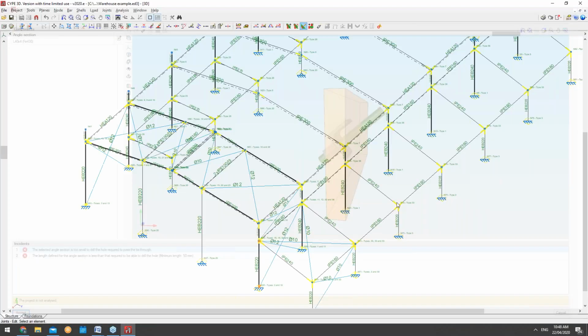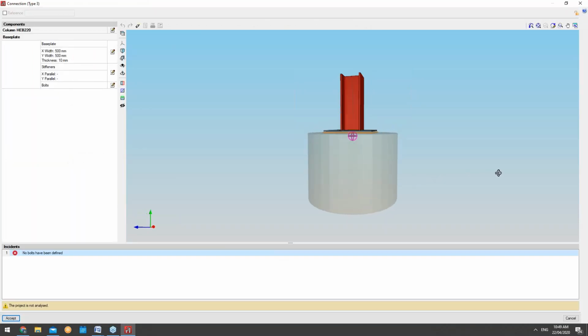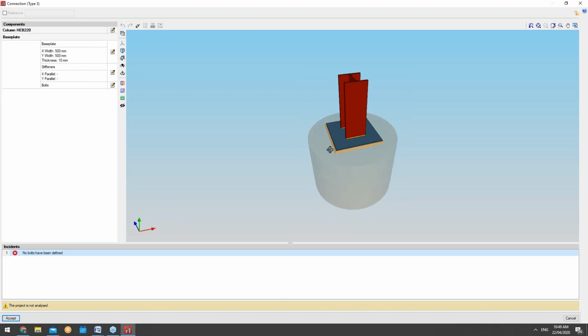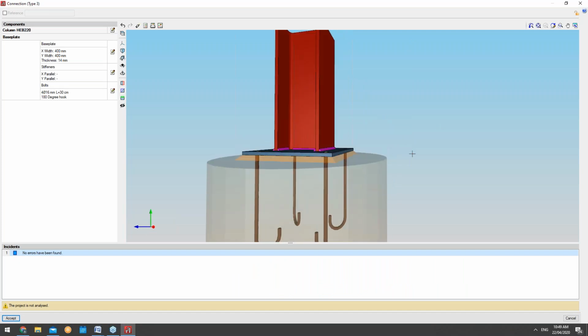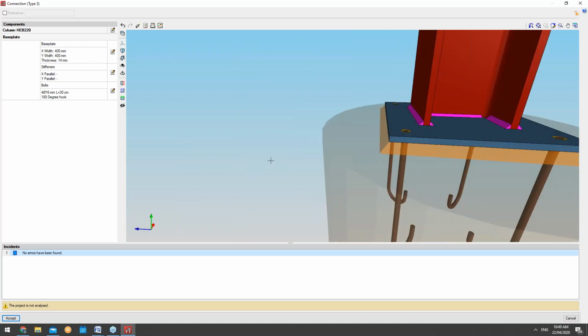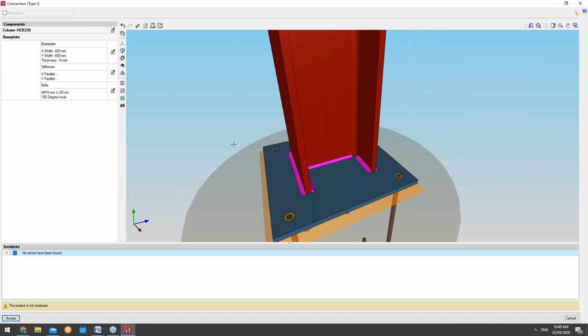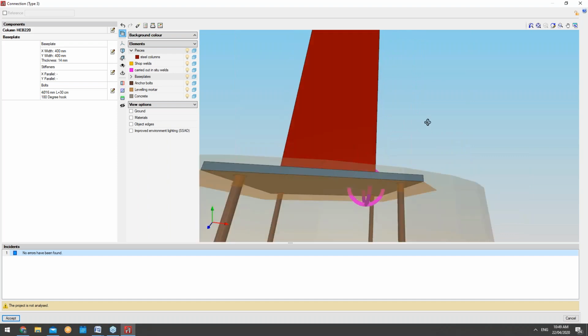This is a foundation connection. Here you can see a base plate that's been defined here. I can design again, view the complete report again, but then view as well the bolts that are inserted in 3D, the stiffeners and the base plate. So these are the sort of connections that we can make within the program as well. The same basic options for each connection that's generated: the detailing, complete report, design, and also the specific viewing options that I have for that particular connection.